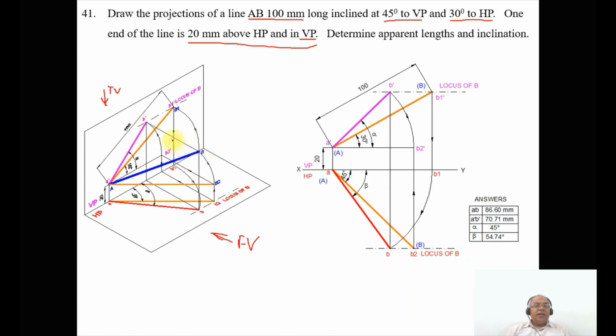Then you are projecting that directly onto the vertical plane when you are looking from the front view. So therefore, you will get it as A dash B dash, which is drawn in the dot line. So that is what we have shown here. As we rotate it in space with capital A as center, taking the radius of AB2, you are rotating such that B2 cuts the locus of B in the front view. So till such height, it will be rotated.